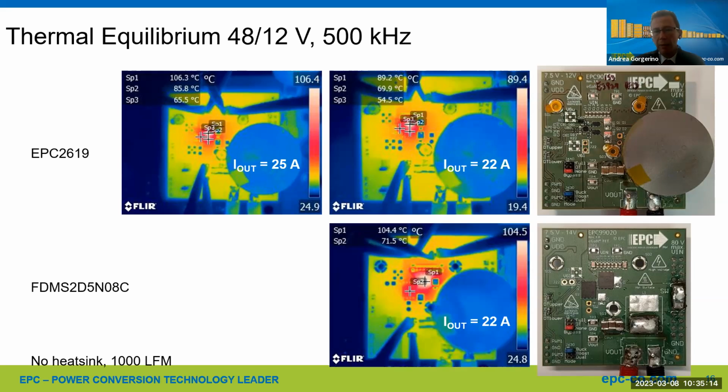The other thing that you have with GaN devices is that they are very linear, because the capacitances still change with voltage, just like silicon FETs, but they change a lot less. So you end up having very smooth waveforms during these transitions. And so although the average might be faster, when you look at a silicon MOSFET transition time, you'll have areas of the transition which have higher dV/dt than others. Instead, the GaN FETs are very linear, with very clean waveforms. We have examples of waveforms on our demo boards, and you'll see there's very little ringing and it's very stable. The ringing comes down to basically the design of the PCB and the power loops.